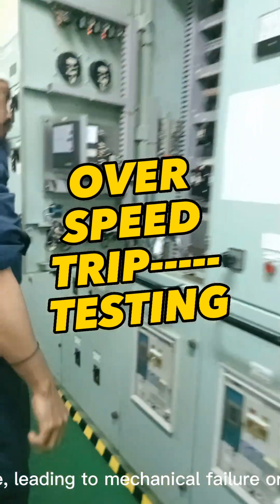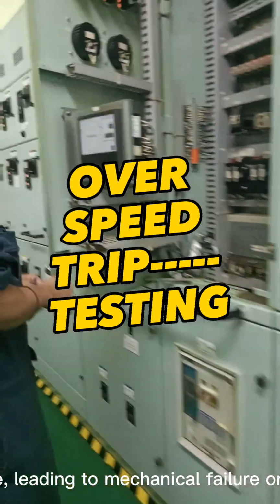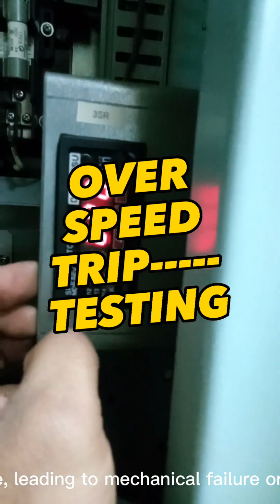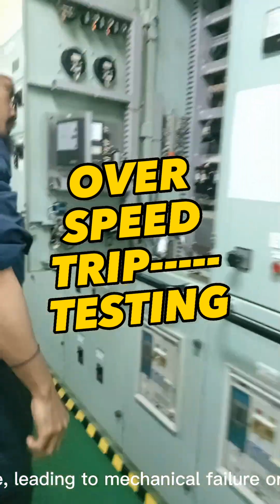An overspeed trip is a safety feature provided on the diesel engine of the ship to restrict uncontrolled acceleration of the engine, leading to mechanical failure or untoward accidents. In order to prevent the speed of a diesel engine from going beyond the preset speed range, an overspeed trip is used.